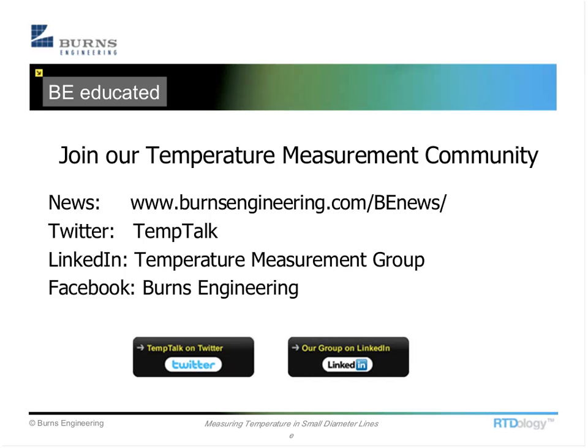For gas type applications, time response can be a big issue, because the typical RTD is going to have a pretty slow time response. It may be a situation where a very small diameter thermocouple may be a better choice just to overcome that time response issue, and it would actually give you a more accurate measurement because of that.